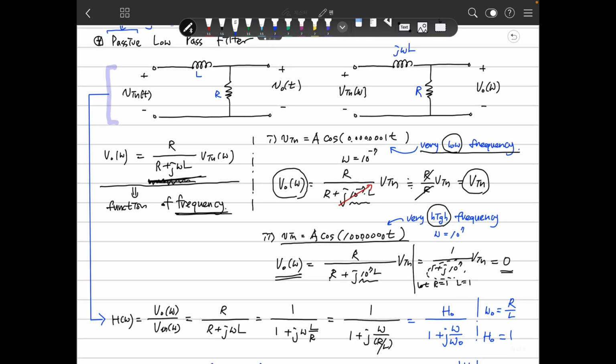In passive filters, the maximum DC gain is 1. With an active circuit using the op amp, you can amplify your signal levels relative to the input. This is the reason we use active filters.